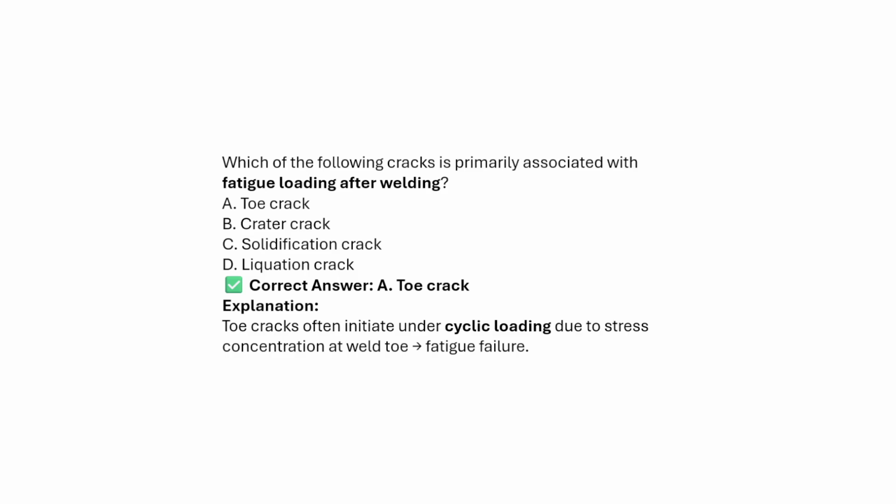Which of the following cracks are primarily associated with fatigue loading after welding? Option A, toe cracking. Option B, crater cracking. Option C, solidification cracking. Option D, liquation cracking. So the answer is option A, toe cracking. Toe cracks often initiate under cyclic loading due to stress concentration at the weld toe, which results in fatigue failure.